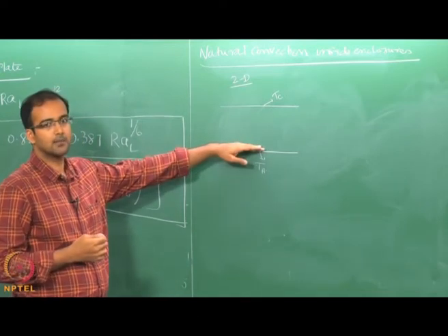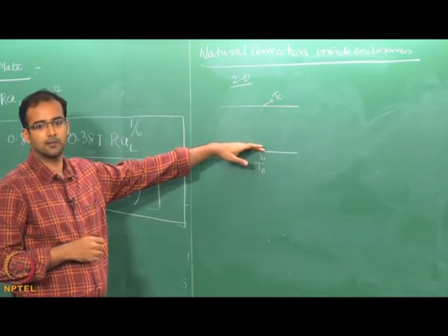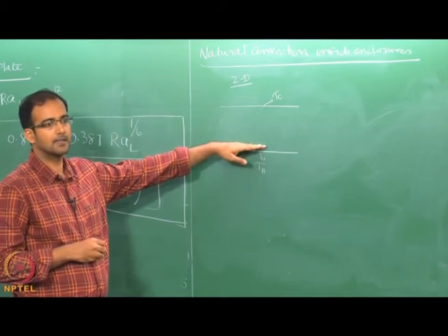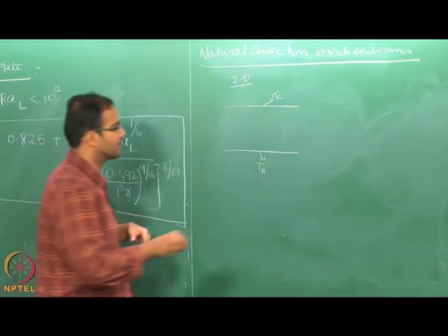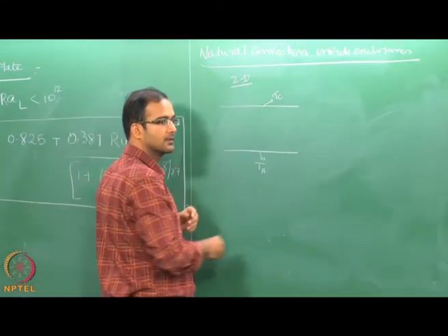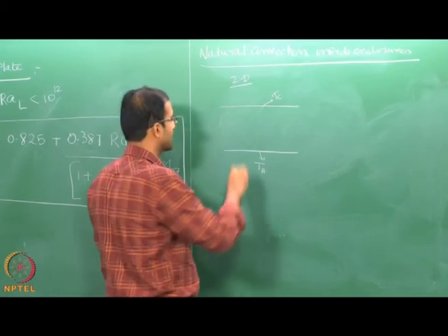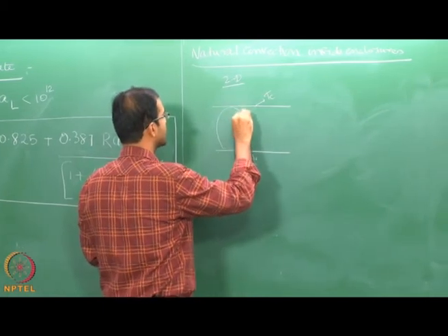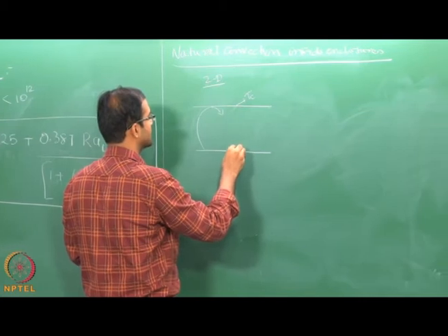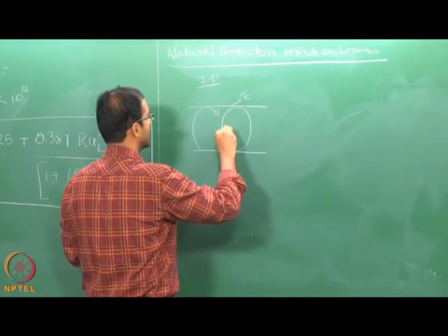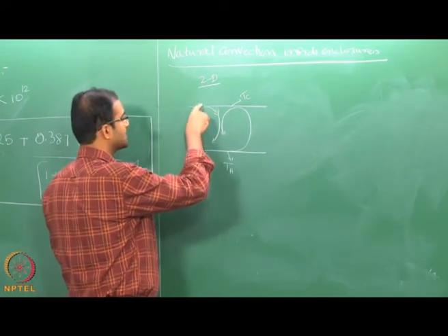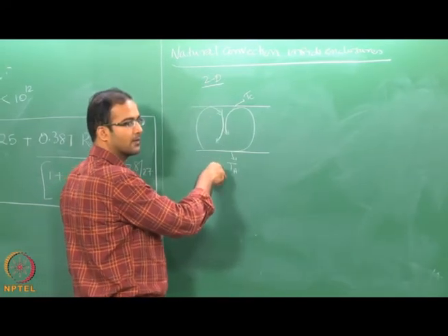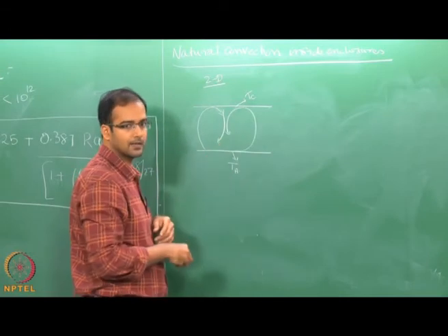So, this will be an unstable configuration: the bottom plate will heat the air and the top plate will cool the air, and therefore the tendency will be for the hot air to rise up and the cold air to descend downwards. In the end, you will get some kind of vertical structures like this, where the hot fluid tends to rise up, cold fluid will come down, and this can happen symmetrically.